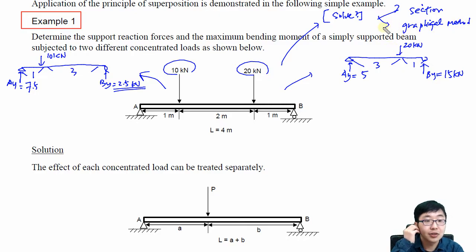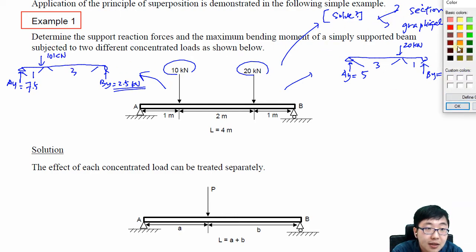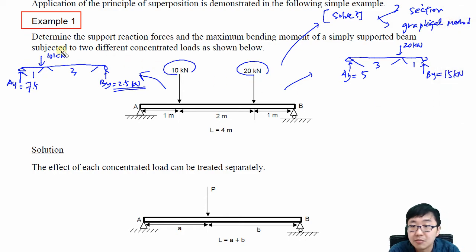So I would suggest you apply the section method, because in this case, based on the applied load, please keep in mind that if you want to adopt the section method, you should cut it here first and here. You need to split into two different ranges, about this range 1 and the other range 1, and in this case cut it here and there, so that you can get two different moments to complete the total moment condition.